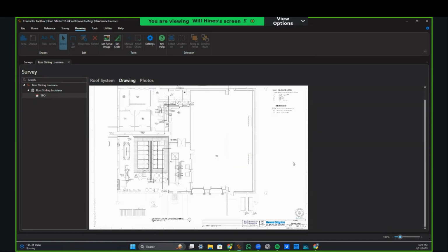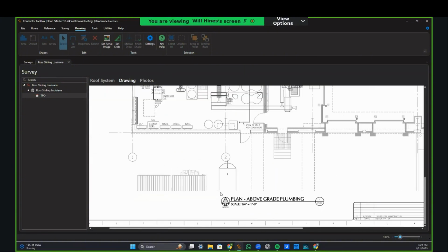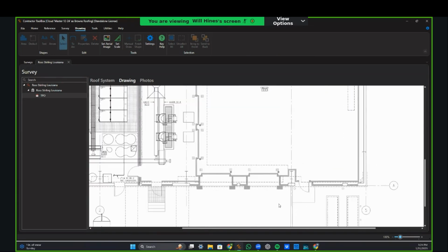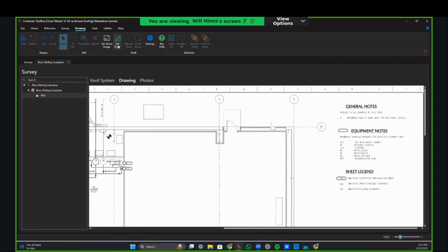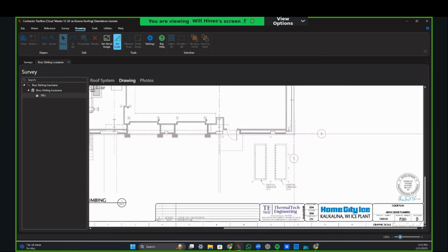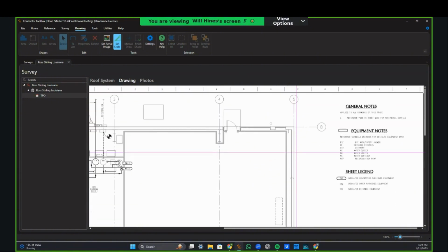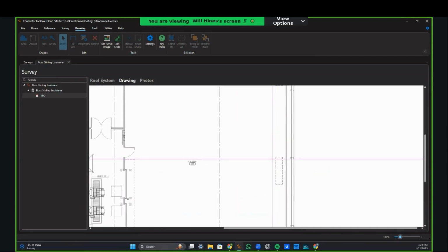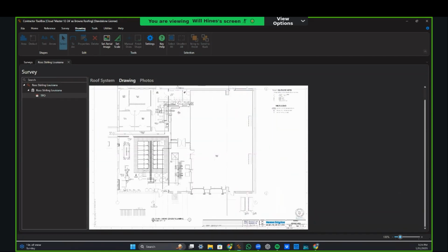And if you need to read any of this info. This isn't really a roof plan. I don't know if they have any. So they do have a scale here. There isn't really a way to set the scale using this in this program, at least currently. So you would use this set scale function up here, and then you would just need a reference measurement of one of these sides. A lot of times they'll have a plan that has measurements along those lengths, and like most roof plans would have some kind of measurement on it that you can set the scale with. And then you can start drawing your roof right on top of this. And that's essentially how you would use a set of blueprints to create an estimate.